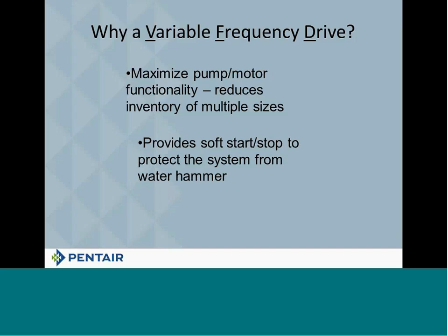Soft start simply means that we're going to slow the flow down and keep the pressure the same. Typically on a across-the-line starting, when you slow the flow down, your pressure goes up and you get a spike. You get a water hammer. Okay? With a drive, you may not get a water hammer at all. If you do get water hammer, it is extremely minimized, and that's why a drive really helps you.